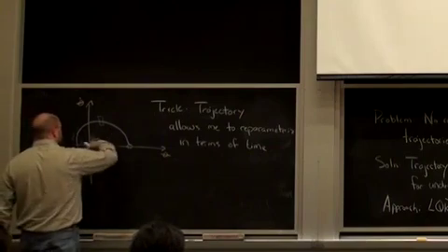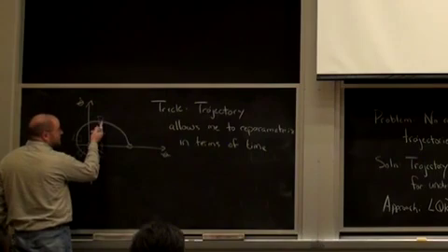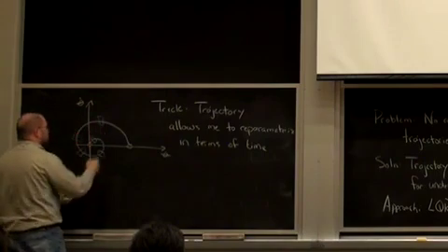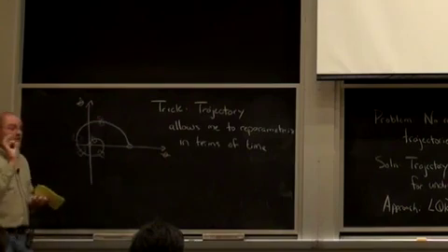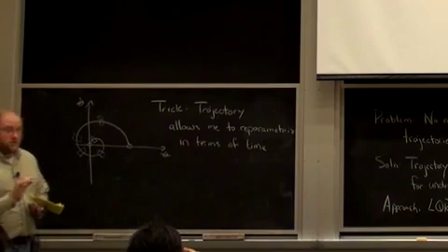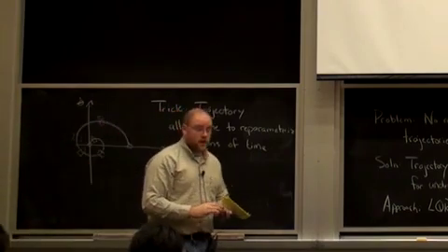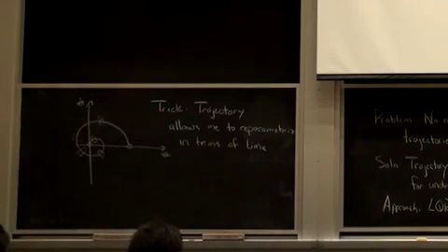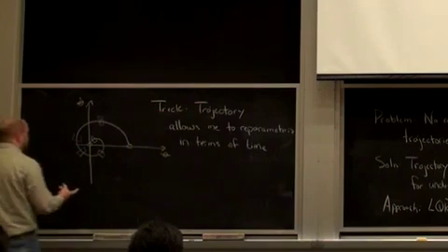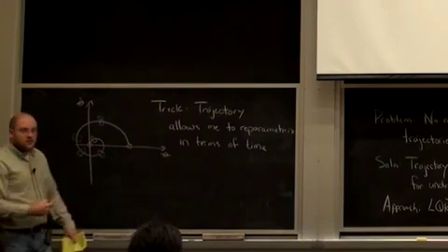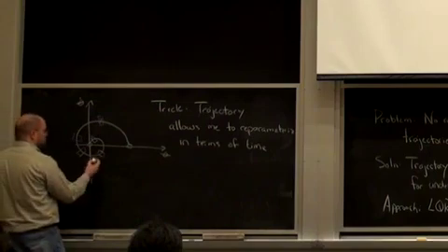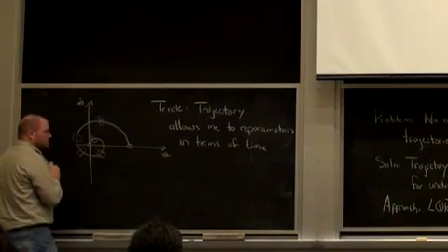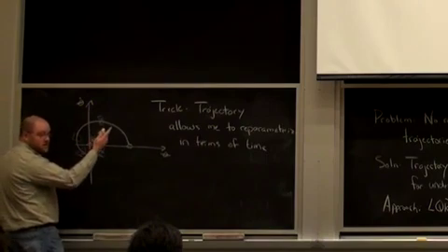And by virtue of taking a particular path through, I can make locally linear models with eigenvectors and eigenvalues that are valid in the neighborhood of the trajectory. Okay. So if you can imagine, even without any stabilization, I could quickly assess the stability of my time-varying linear model. And trajectories in this linear model may converge to the nominal limit cycle, or they may diverge, depending on A and B.